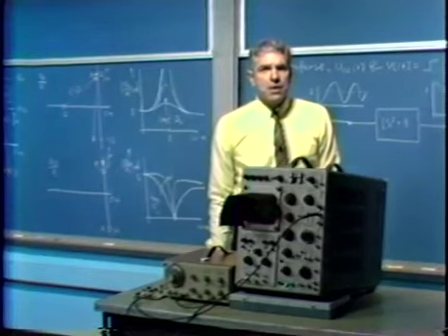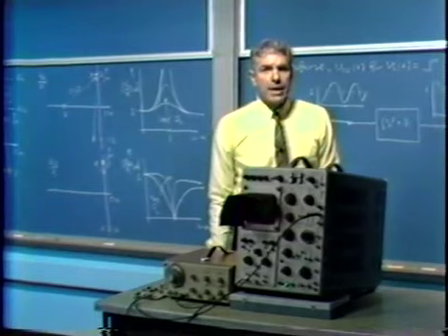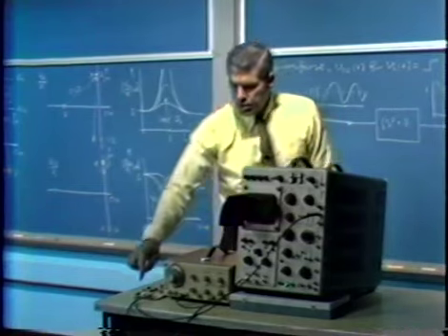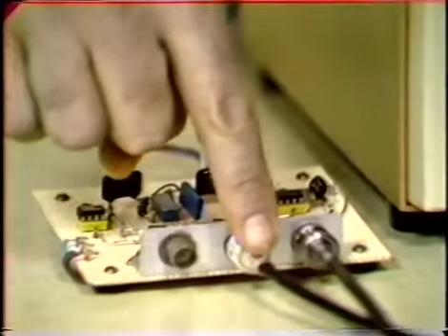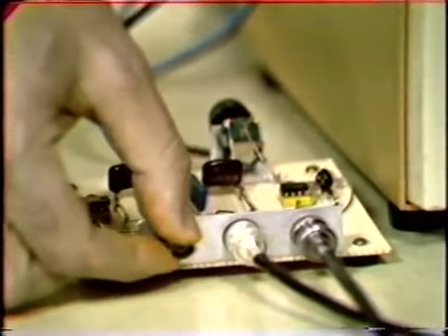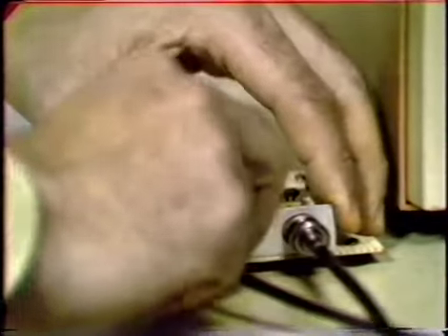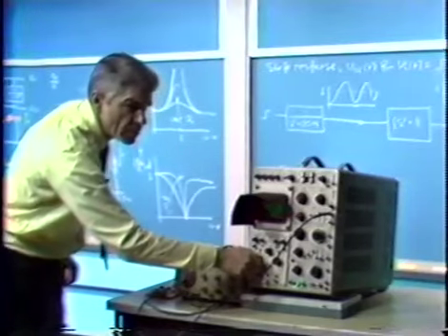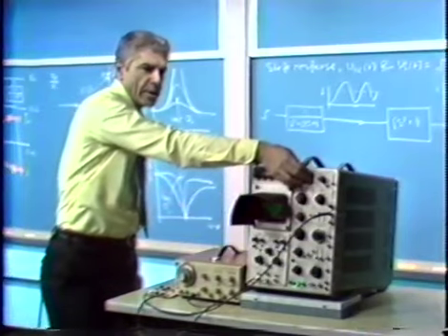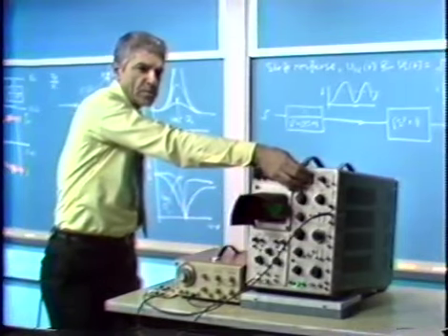We can change our configuration since both the one and the two outputs are brought out in this demonstration. This is the one output, which runs to the oscilloscope. We can change that lead to the two output and then look at the same sort of responses again. So we'll simply move that over, and I've got to change the sensitivity on the oscilloscope. So let me do that. And let's erase our first response, in other words, the one that was the bandpass amplifier. And now let's look at these plots.